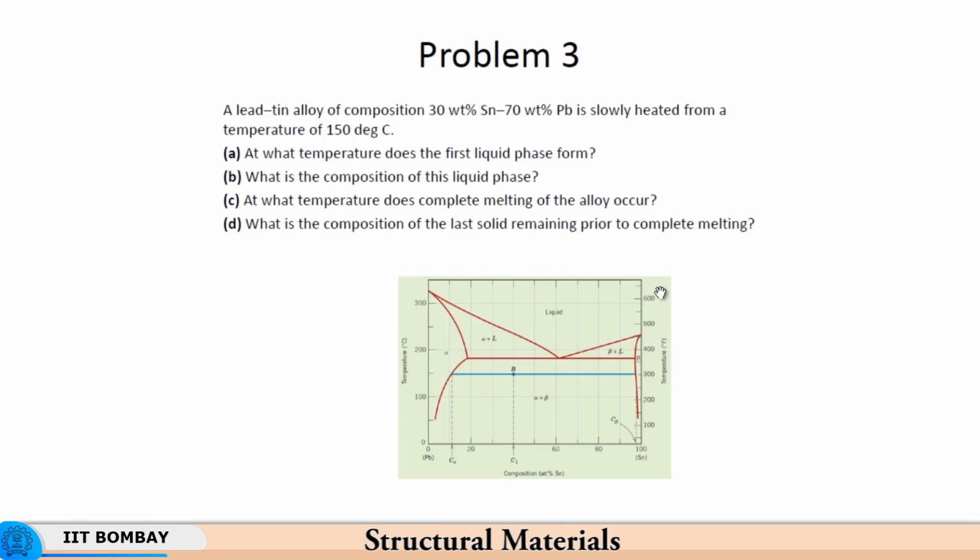So as you go on melting it, the proportion of tin in the solid is going to continuously decrease, because just at the time of melting you have this, and then as you go on melting it further and further, you have some alpha with a very large amount of tin, and the liquid which contains a relatively decreasing proportion of tin.